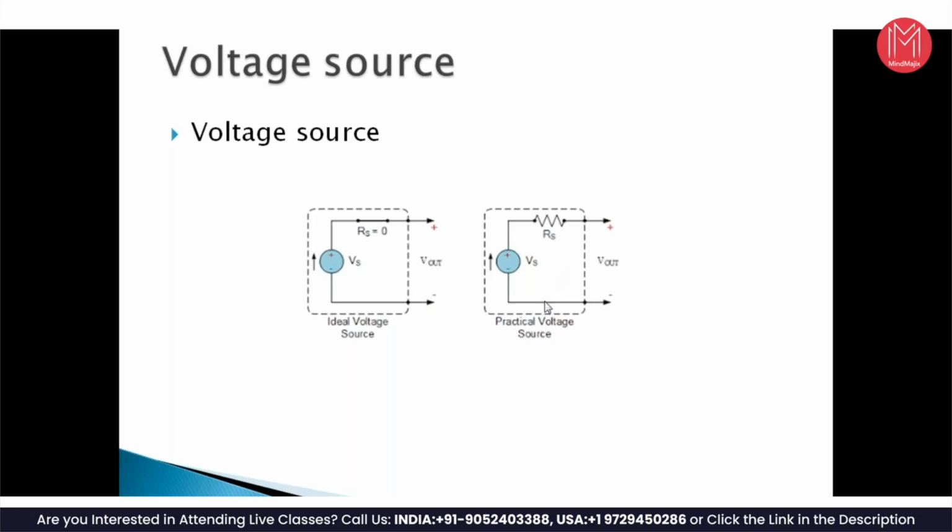This is basically observed. So most practical power supplies are designed for a specific voltage. It can supply up to, let's say, 2 amps at 5 volts. That is the specification that's given. That's because this resistance is small, and if we consume a little more than the rated current, then the voltage drops a little. And this is how the voltage source is.